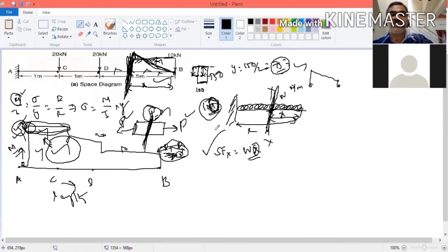That is the meaning. If you want to find bending moment at x, then what is the equation? What is bending moment? Force into distance. What is the force acting here? Load per meter is W, multiplied by x will give the load. This is the load into distance.